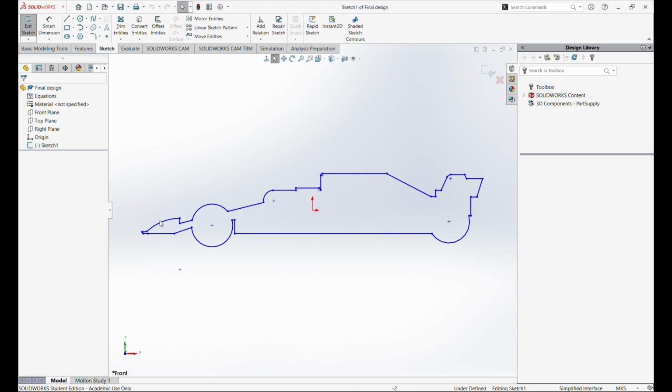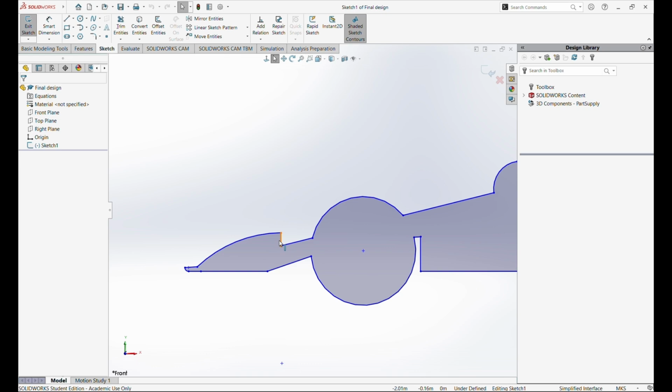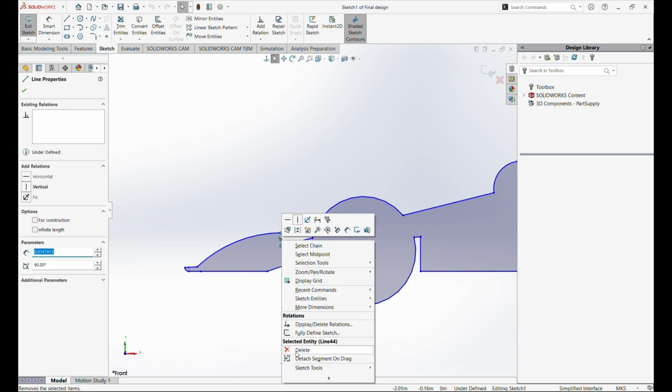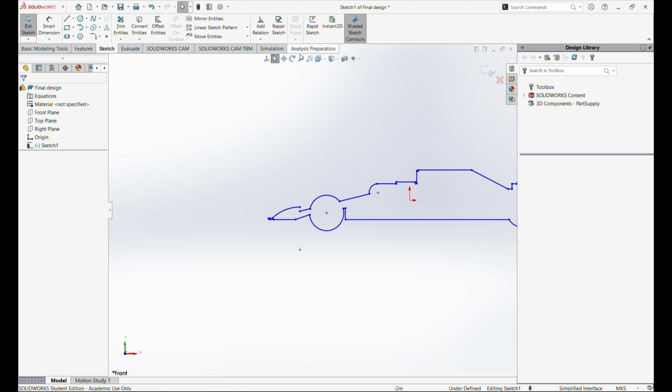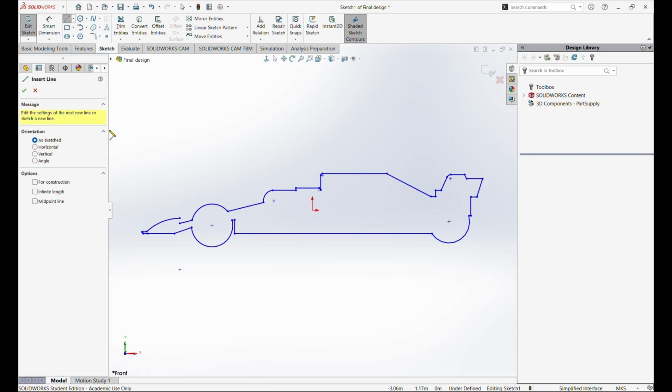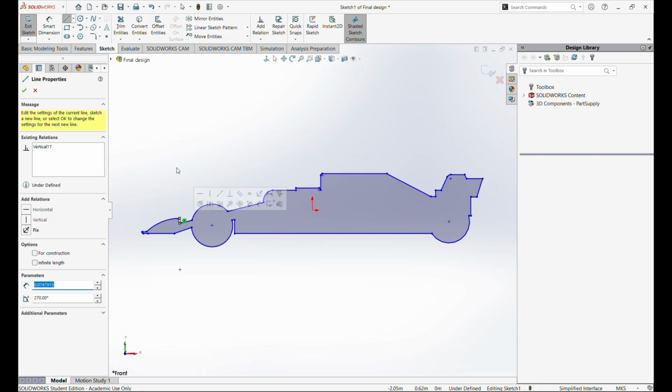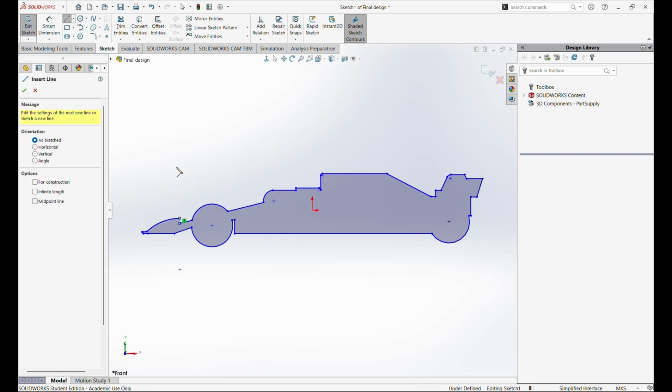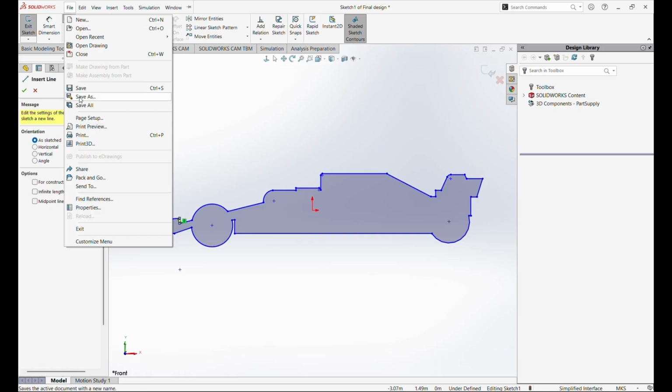To check that, you can click on shaded sketch contour and it gives a shaded region over here. If the body is not closed, look at this, I remove this line just to make it unclosed. Once I delete it, the shaded region is gone. Now it doesn't have a shaded region even though shaded sketch contour is clicked. So again I click on the line and make it a closed one, and the contour appears on the figure again. This is how I designed the project.